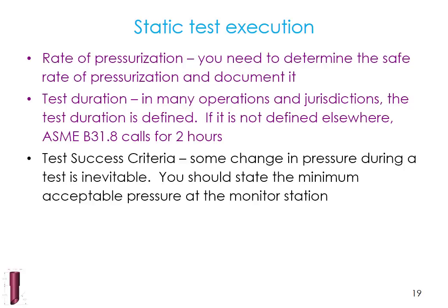You need to define success. Some change in pressure during a test is inevitable, and you need to state the minimum acceptable pressure at the monitor station. Some people allow the introduction of more test fluid to make up for temperature change, and I don't do that. I find that way too imprecise.